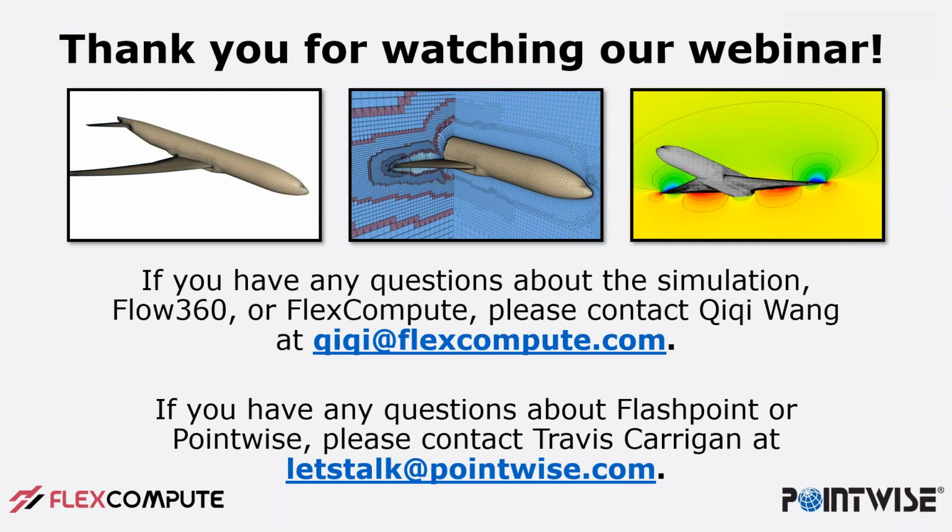Chi-Chi, can Flow 360 do time accurate LES? We do time accurate flow solutions, so that's unsteady. We routinely do detached eddy simulation, which basically uses a RANS model close to the surface and LES away from the surface. We have implemented delayed detached eddy simulation, but we don't routinely do actual large eddy simulation.